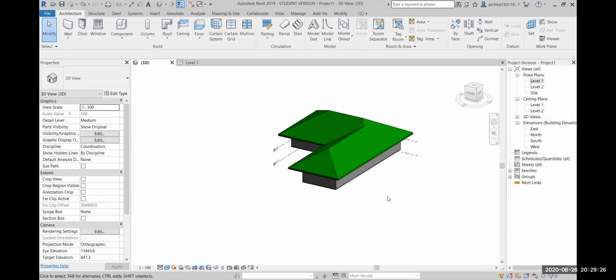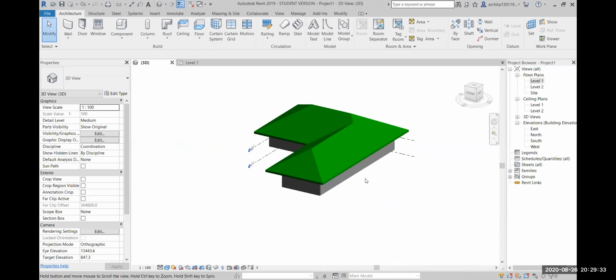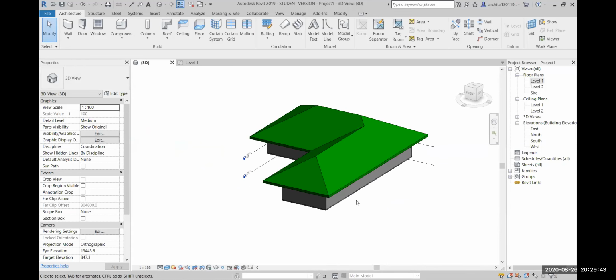Why I wanted to create it is because I wanted to show you the different visual styles which are available in your Revit. We have already known the hidden and the shaded portion, but again I'll make you go through all the options. So let me just hide this. Under this bottom ribbon, one is scale, next to it is the detail level, which we have already seen.